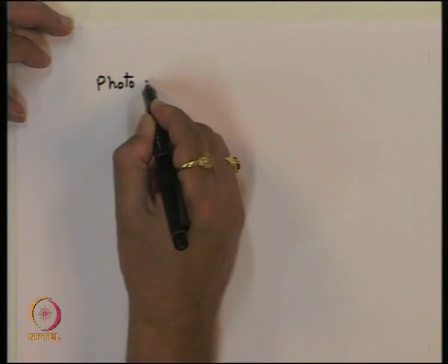Now the detector essentially is a square law device. As you have seen, inside a photodetector we have the photocurrent which is proportional to the optical power. But now the photons which are generated inside the EDF will be added with the signal, and the signal and the noise photons together are going to fall on the detector. So in this case, if you ask what is the photocurrent which is going to flow, we will get the photocurrent in the detector.